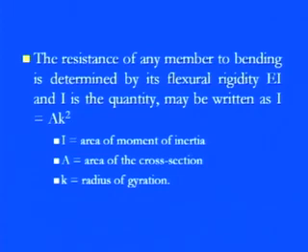and this is a limiting factor, I should say, under load applications, through which we can say that this is the resistance that can be provided by the material. Again, this EI is very sensitive to which material you are using and what the shape is. So E is the Young's modulus of elasticity, as I told you, and I is the quantity which can be written as A K squared.